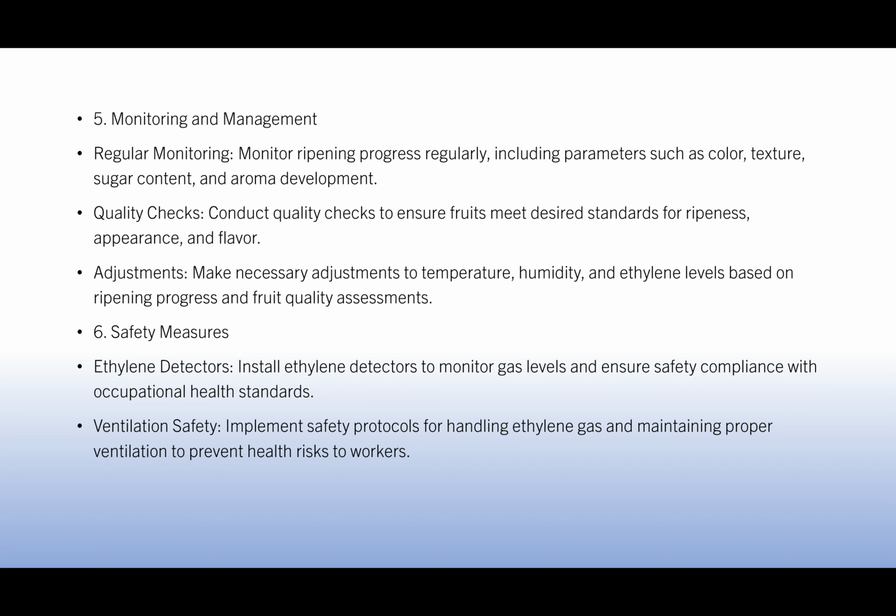So we monitor it and manage it. We adjust any issues with temperature, humidity, or ethylene concentration. And we use different ventilation safety mechanisms and ethylene detectors to know how much ethylene is in the room and to make sure that it's ventilated properly. Because ethylene can actually affect health workers, the ventilation is a key for those workers as well.